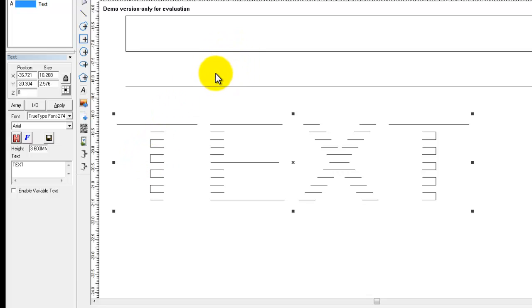We weren't able to show you that on the square because it was just one object, but the way this fill works with the dashed lines is that it will stay on when it turns the corner to the left and the right, or the top and the bottom extremities of the object. However, when it comes across the object, it's going to go completely across, come up to the other side, and come back across. So when it processes this object, it's not going to do one character at a time. It's just going to come across the entire object as it marks and turn the corner. It stays on, so on and so forth, until it processes the entire object.